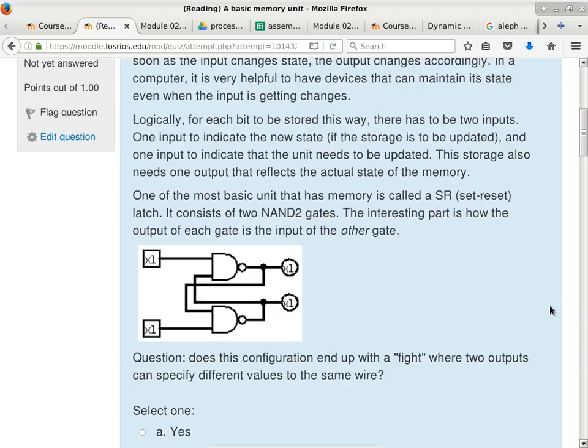Are there any questions about the schematic or the picture or how things are connected? And for the first time, this cannot be translated into a Boolean expression, because Boolean expressions cannot handle that feeding back mechanism. Whereas before, when you look at the adder or the subtractor, we can express everything as a Boolean expression, but not this one.